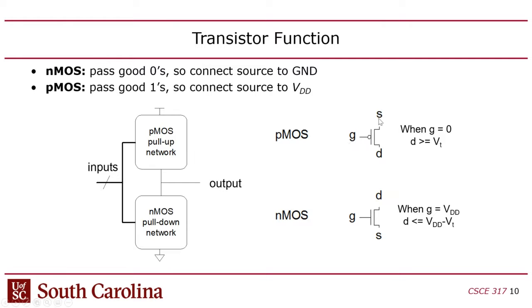Likewise, the voltage of the gate versus the source will also be negative because the source is going to be connected to VDD. So if the gate is anything less than VDD, it's going to give you a negative voltage on the gate. The voltage of the drain versus source is negative, and the current from the drain to the source is also negative because you're measuring the current from the bottom terminal to the top terminal.